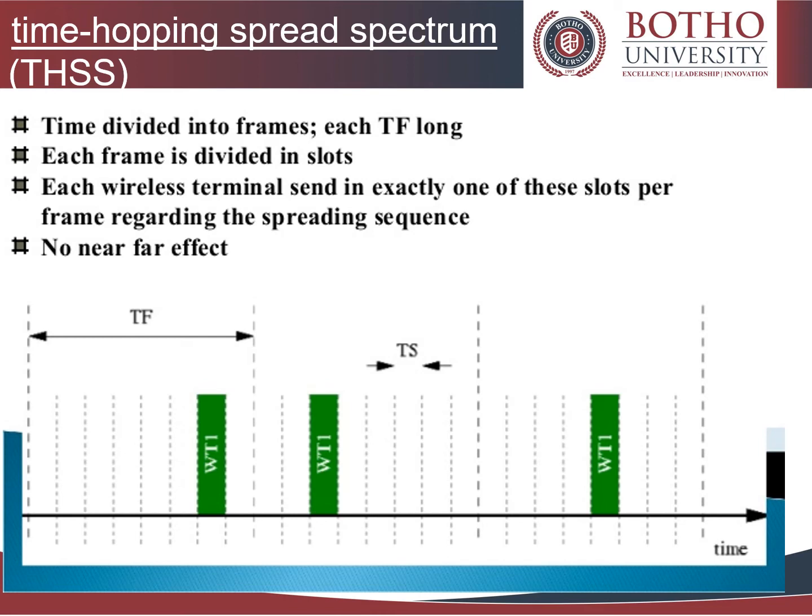Although often used to form hybrid spread spectrum systems, TH is strictly speaking a non-spread spectrum technique. Spreading of the spectrum is caused by other factors associated with time hopping, such as using pulses with low duty cycle having a wide frequency response.